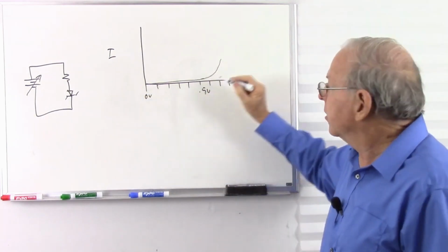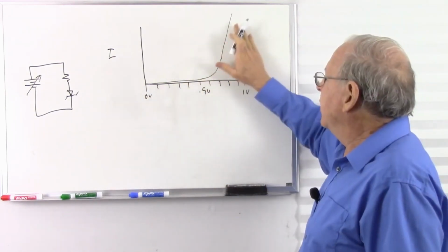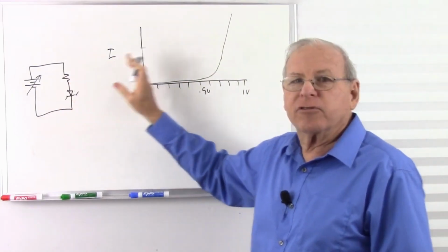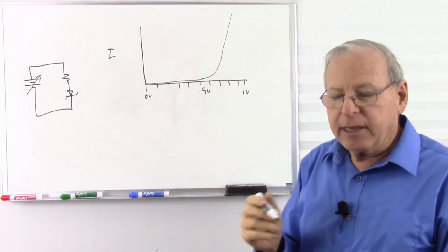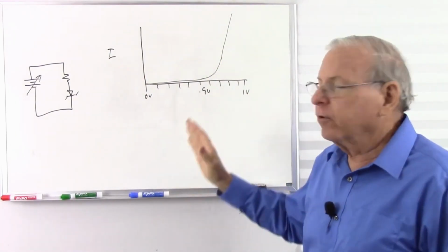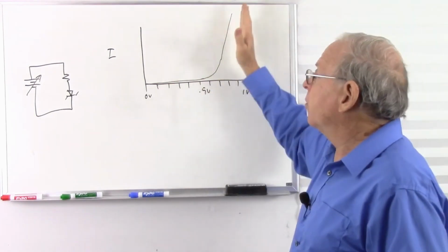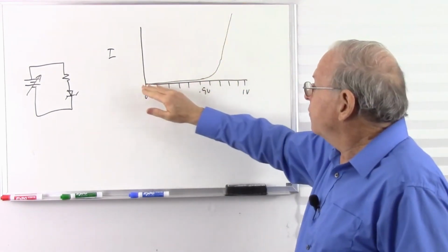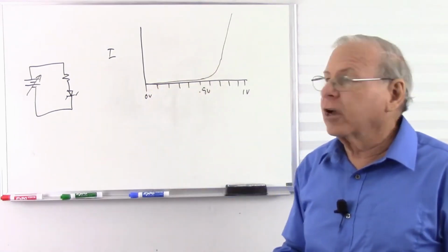So we get this logarithmic curve. And after we pass 0.7 of a volt, it's going to go cascading up, and a tiny increase in voltage is going to give us a tremendous increase in current. And it'll typically be between 0.7 and 0.8 volts, but a big Zener diode, which they do have, might have more, just like any other diode. So forward biased, our Zener diode just acts like any other silicon diode.